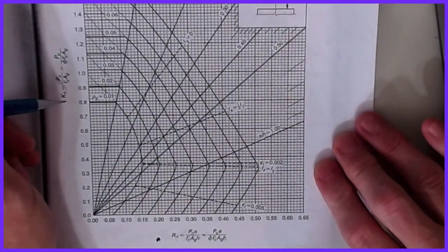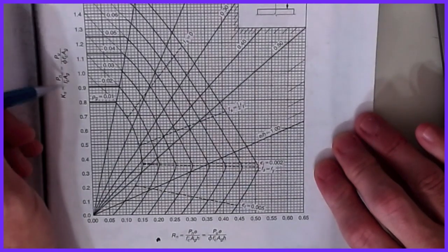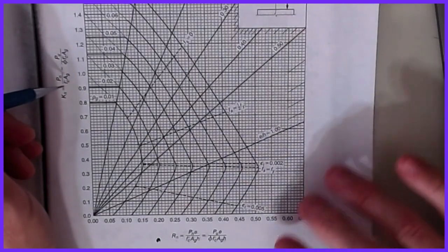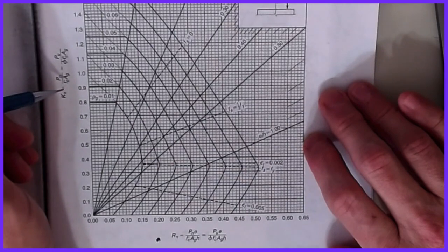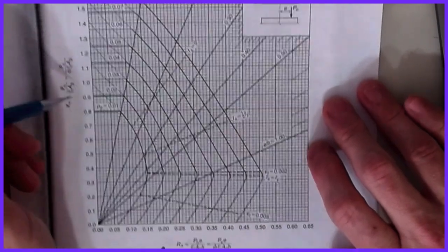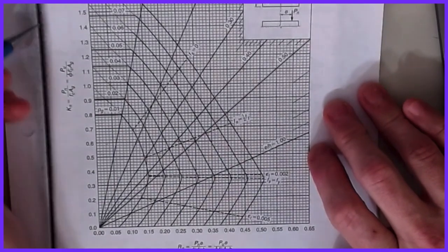The Kn factor is going to be the axial load divided by f'c divided by Ag. So this is almost an axial stress kind of calculation, the ratio of that stress to the f'c compressive value. And you can see that those values go up this axis. On this diagram are a series of